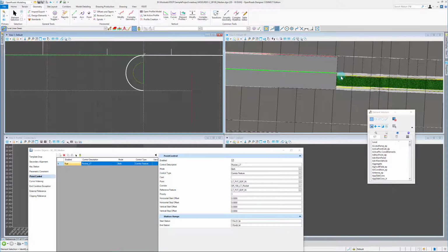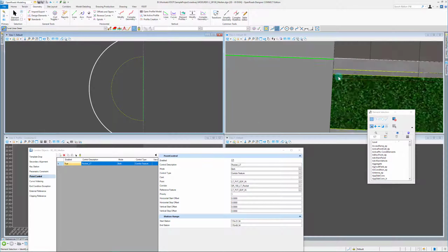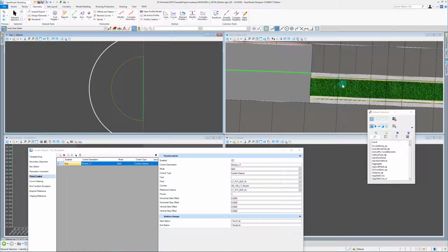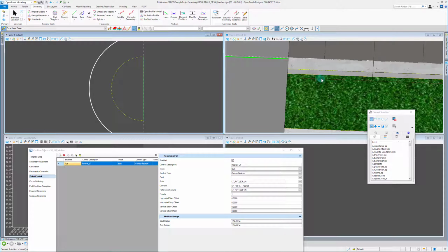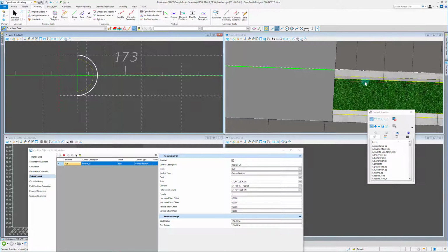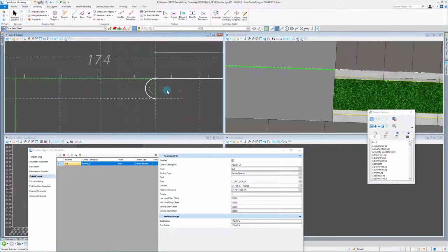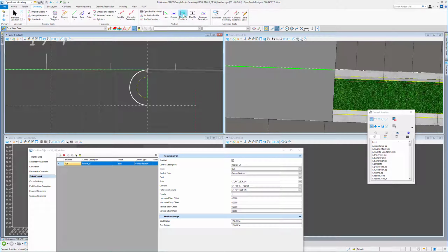So I can't quite draw the line from here to here because since we have a left turn lane, that crown is now here. So typically on these smaller noses where the crown's right about there, I don't really worry about adding this additional line here because it's kind of just going to fix itself. Not a huge deal there.